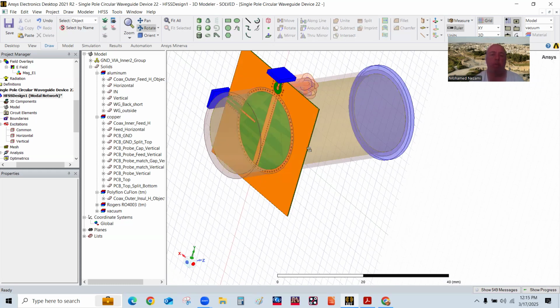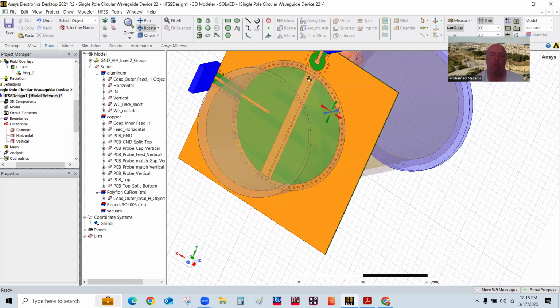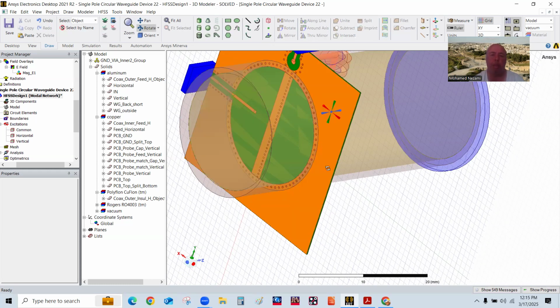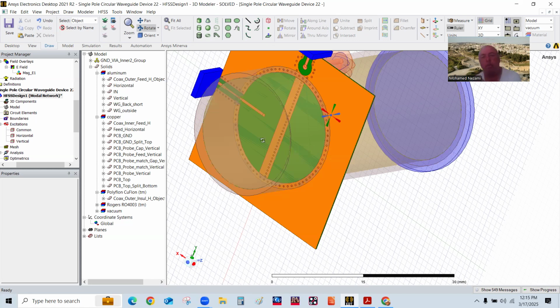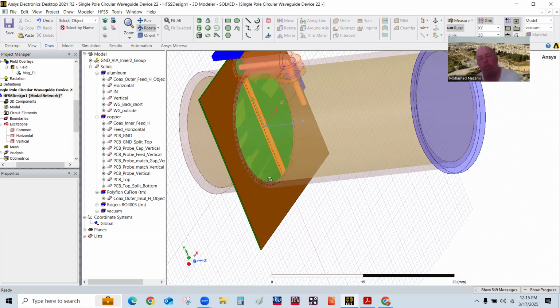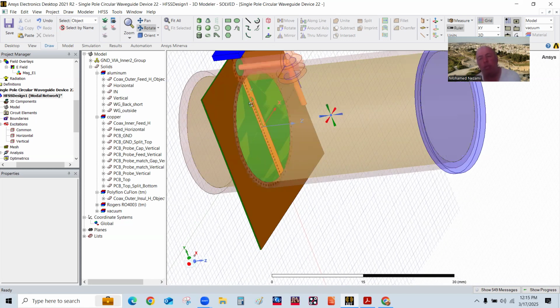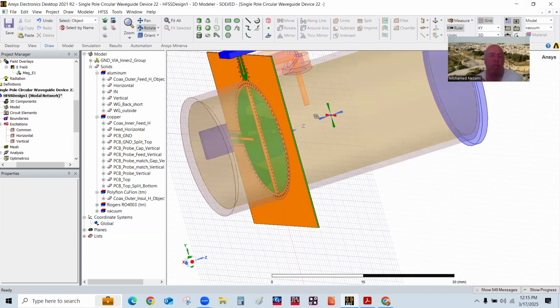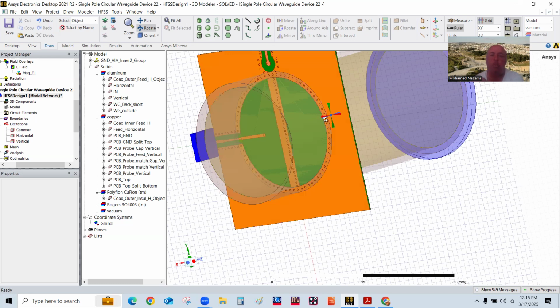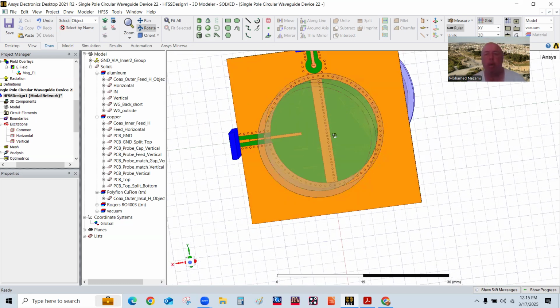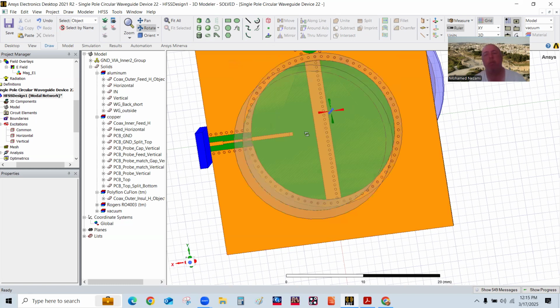for mechanical rigidity. So all I did is I printed this, and a lot of times some people don't print it on the other side. They just print basically ground on one side, which is the back side where this is a quarter wavelength. But what I did is I said to myself, no, let's just put that one, and I stitched it with vias spaced about a half millimeter.